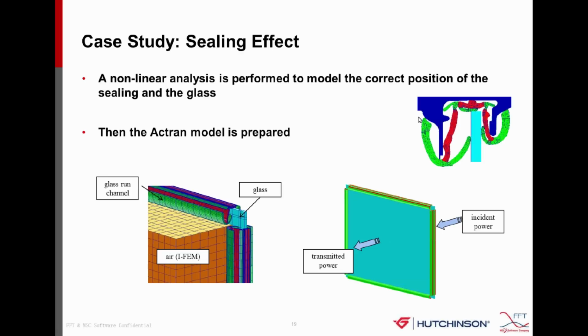So to run this project, we have gone through 2 steps. In the first step, the MARC software, which is a nonlinear finite element modeling software, was used to simulate the seal and to calculate the position of the sealing and the glass.